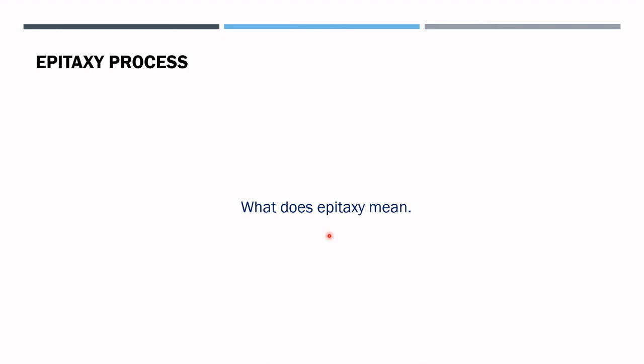That thin crystalline layer is arranged on top of the already existing bulk single crystal. That is epitaxy. So an epitaxial layer will always be much thinner compared to the thickness of our bulk crystal, and this is a very important and interesting point of the epitaxial layer.